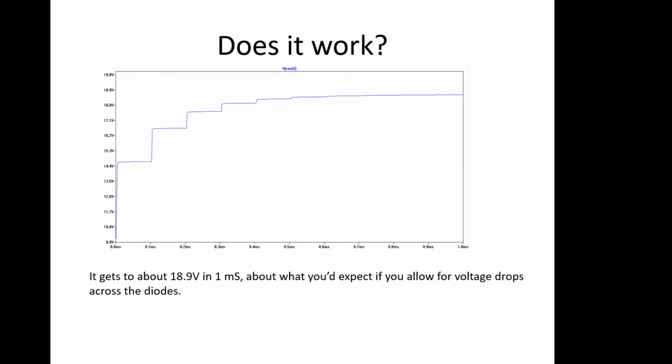So when you turn it on from nothing, with the square wave going in, you can see the frequency of the square wave imposed on this, and you can see that it charges up quite nicely in the simulator and gets to 18.9 volts in 1 millisecond, with I think it's probably a 10 kilohertz frequency driving it. Okay, we're expecting 20, but this is the real world, remember, and we've got some diodes, so there will be some diode drops included in this.